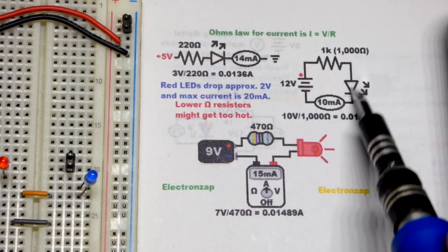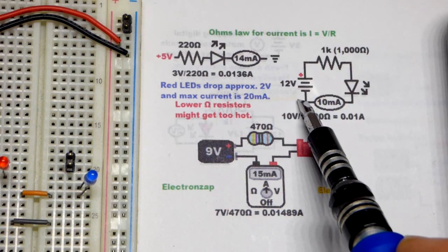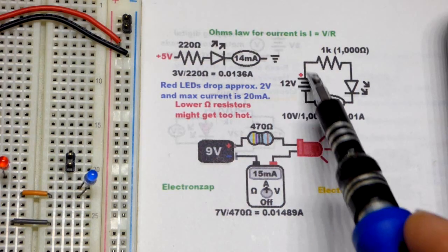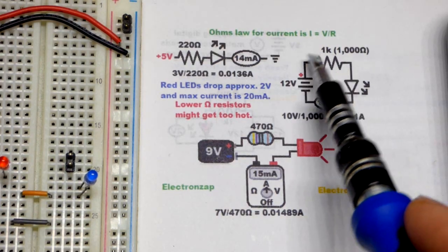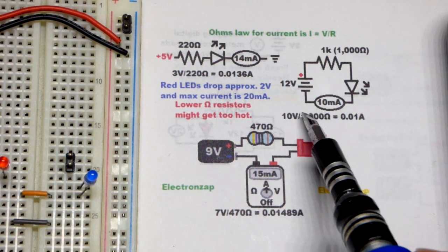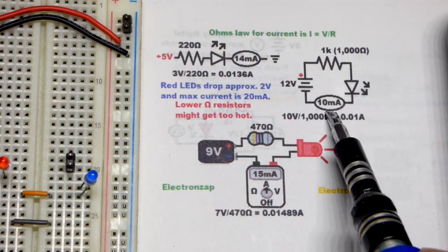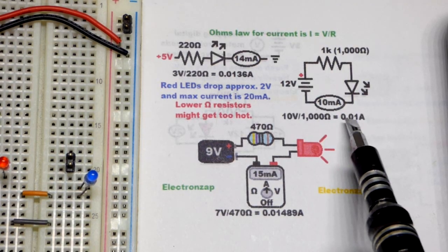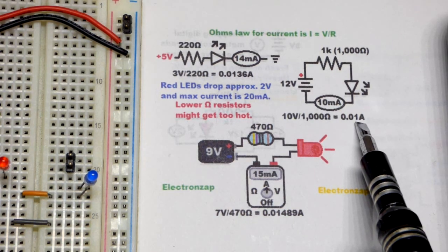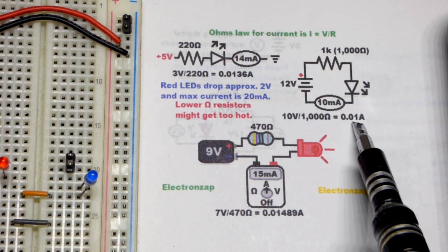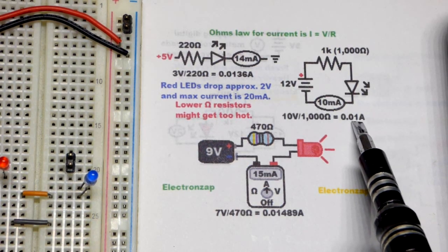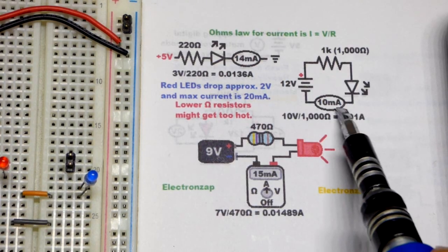That's how we look at circuits, positive to negative. That's just originally what they thought was going on, and that's how things are written. But in reality, you have electrons going from negative to positive. So it's the same thing. There's a certain amount of electrons moving, and that's indicated by the amps right there. So you do the math in amps, but then you convert it to milliamps. A milliamp is 1/1000th of an amp. So you can see this is 0.01, and you take the decimal point and move it over 2 spots, and then you have milliamps.